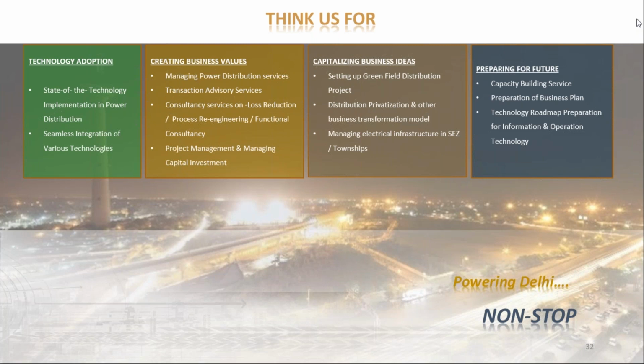I fully agree. Most of the people think that only the selection of the conductor based on the ampere rating will solve the problem. It is not. So this is the planning part. They have to do it, and then they come to the conductor type, which quality, which cross section, which impedance, which is offering less impedance, which is giving me a good load factor, how I can lay it, soil resistivity, and these kinds of factors all come later on when they are installing. I agree with you.